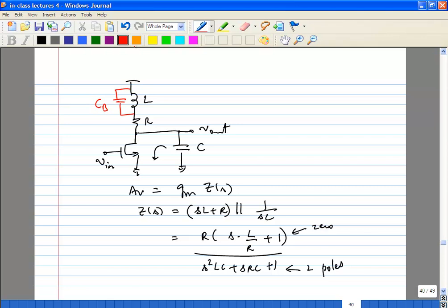It's called a bridging capacitor because it bridges across the inductor. What happens is there will be some resonance between L and CB that also helps to boost the bandwidth. And you can find conditions on CB value and L value for the same conditions we put in before: maximum bandwidth extension, maximally flat, and so on.